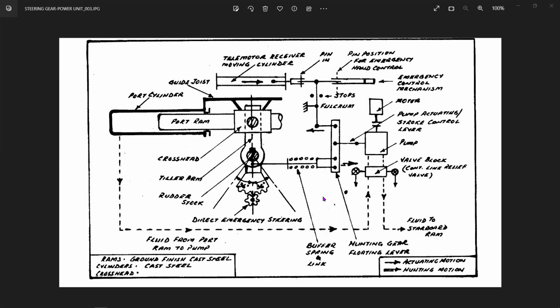So you see, there are a lot of moving parts. You have got one pin over here, you have got a lot of joints over here. So this mechanism was highly unreliable, because it would lead to mechanical wear of all these pins. This buffer spring used to break sometimes. This control lever used to also get jammed if it was not lubricated properly.